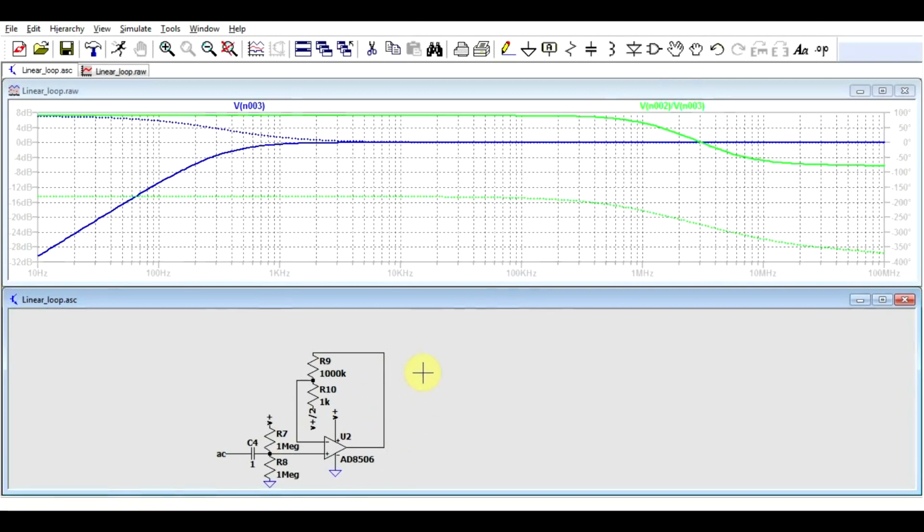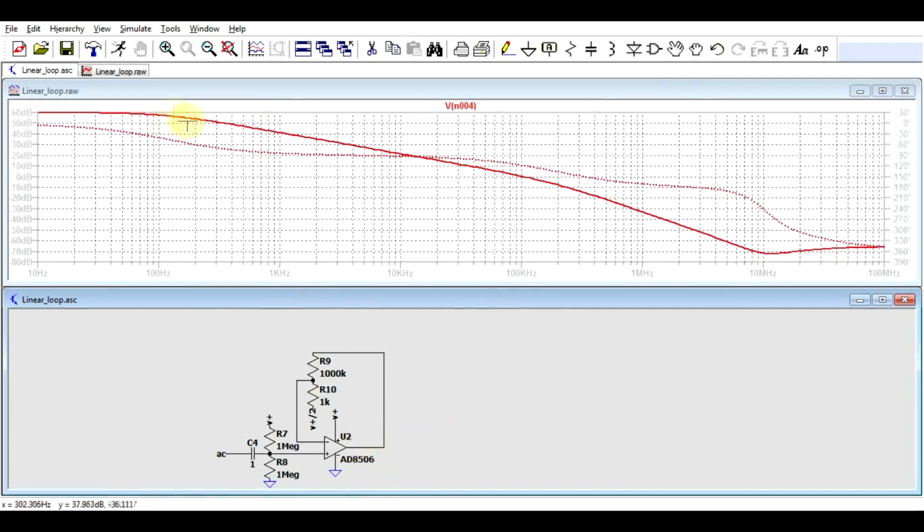Now another thing to keep in mind when doing such simulations can be highlighted with this example. So right here I've got an op-amp configured as an amplifier, and this time I'm injecting the signal through a 1 farad capacitor, so it doesn't have to be a realistic capacitor. And I've done this just to eliminate any sort of low frequency misbehavior. Now we can see that since I've got the 1000 factor amplification, I get 60 decibels. So exactly what we expect.